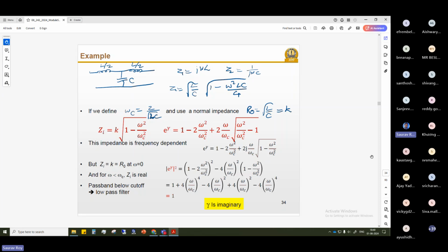But here mainly we are bothered about only alpha and beta parameters, okay, because we are not going to actually calculate how much actual attenuation happens or how much phase shift actually happens. Those we will do with s parameter only. But if you have to analyze things with intuition, there these things will be required, okay. Okay, correlating mathematically and finding out alpha. Yeah, understand.